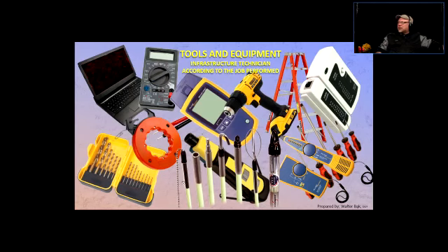Now, fiberglass rods. They are fiberglass sticks. And notice that every stick has the female version of a thread on one side, and the male version of a thread on the other, so you can stack them together. They're very useful if you see a long cable tray. You can just keep stacking them and pushing until you get to wherever you pull the wire or a string on the other end, and pull it back.